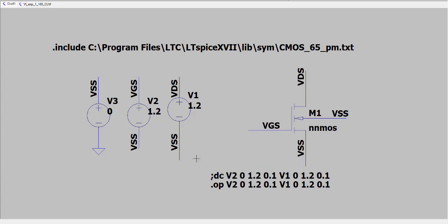Okay. So you see, this is a basic MOSFET. This is an NMOS. Okay, and I have applied these voltage sources. Using these voltage sources, I am applying a gate to source voltage so that I am biasing the MOSFET, right? So we have the VGS, we have the VDS. I have kept the names as they are, just like we write in the formula. So you all know the formula, so keep that formula in front of you. Okay. So we will see how we get the DC characteristics.